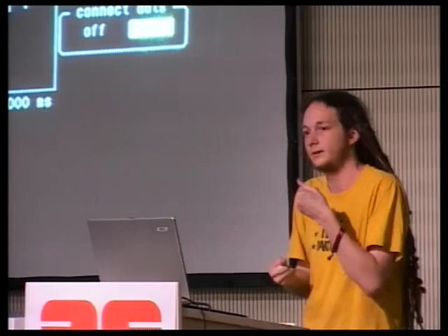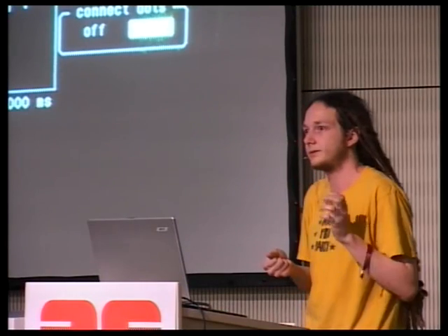Looking at a scope, you can see the timing. And once you initialize it, it's waiting for 0x80 to be sent across, because it needs to figure out the timing with which it's going to speak. And then you can view the conversation as bytes going across the wire between the 2 chips. And I'm going to refer to bytes as packets, because that's sort of how things work.